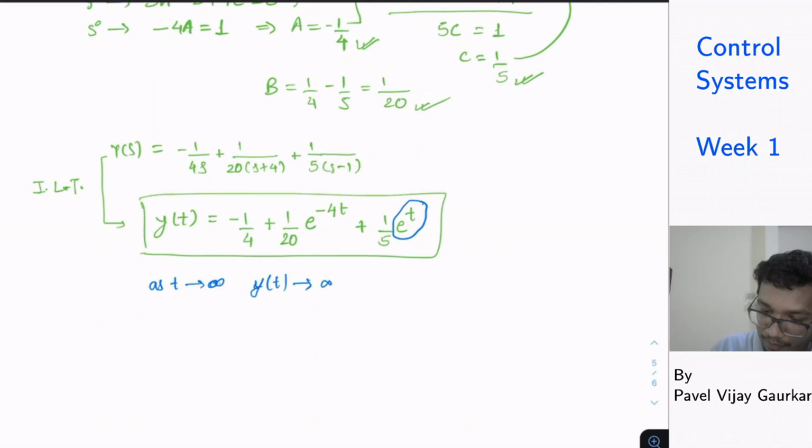There are certain systems that can be termed as unstable systems. For example, you take one tank and you open a tap in it. After some time, the water will start overflowing. That means that the system is unstable. There is no value to reach per se, mathematically speaking. Of course, there are physical limits, the tank's volume will get filled. But if you derive equations for that same thing, you will end up getting a first order system, which is an integrator.